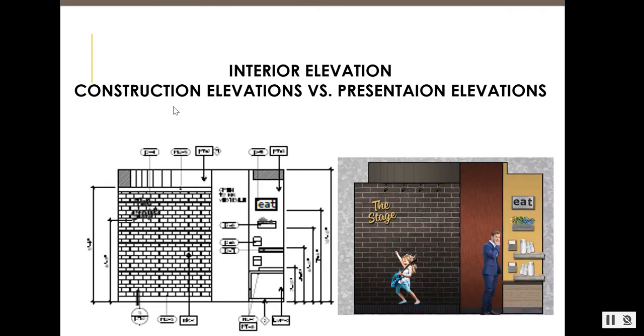Interior elevations, construction elevations versus presentation. Here you would see what we would call an ID elevation. This is very geared towards an installation for a contractor. A presentation elevation is geared towards giving the client the visualization of what their elevation will look like, and it is used for a selling tool. So you really put in a lot of graphics and make it come alive for them.